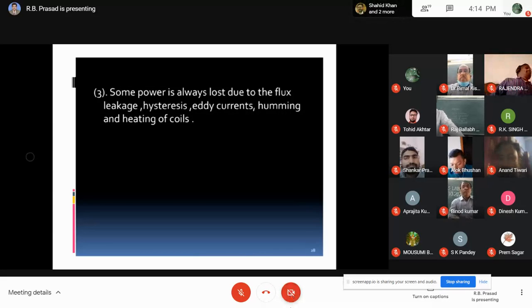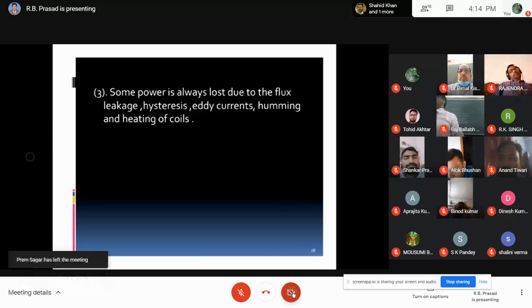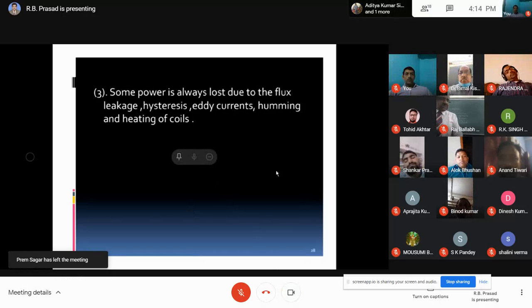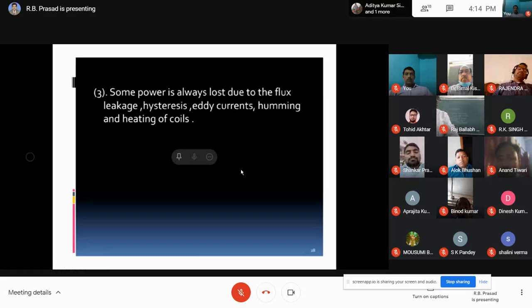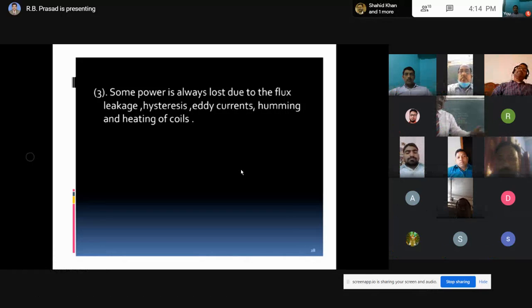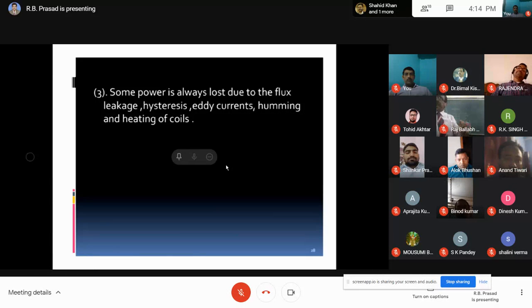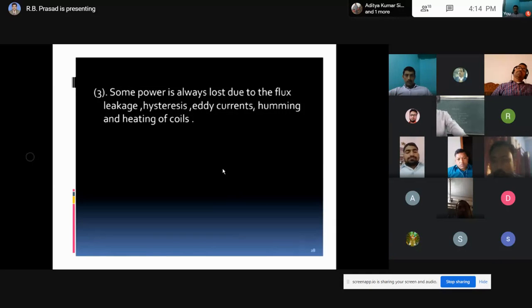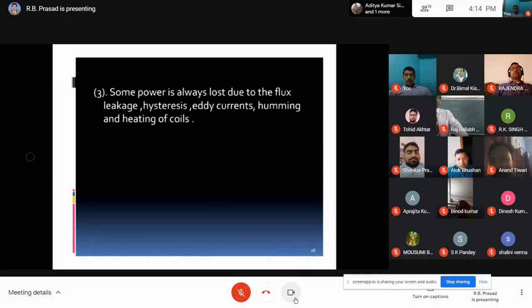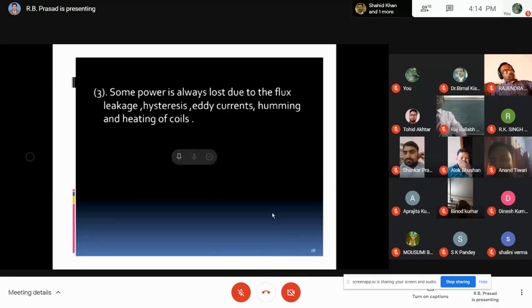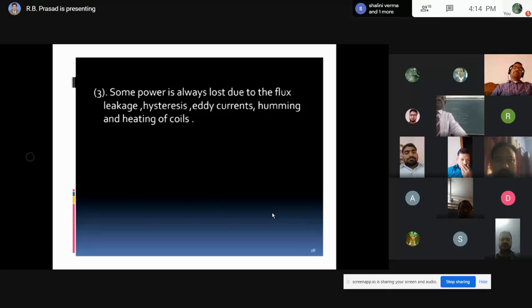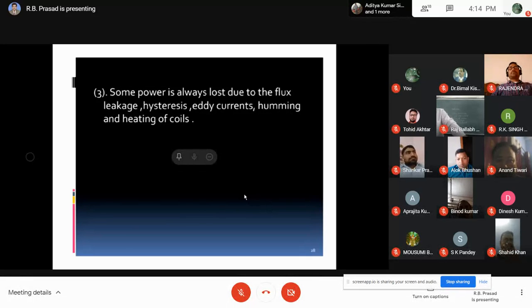If you are passing by and you look at a transformer, a humming sound is coming out. Sound is produced at the cost of electrical energy, the alternating current applied to the input of the transformer. And the humming is due to the looseness of the binding of the coil on the core material.